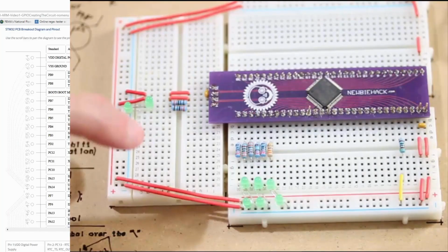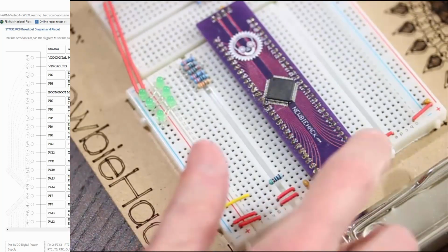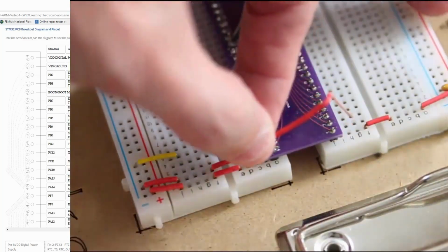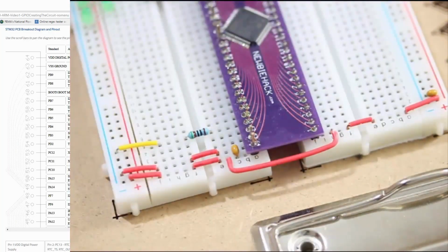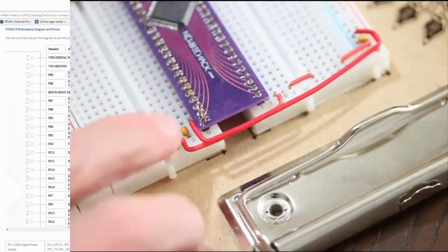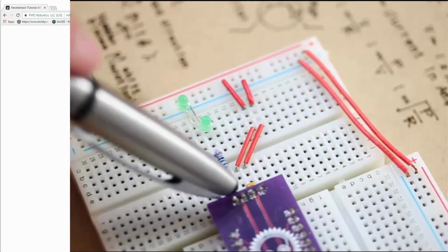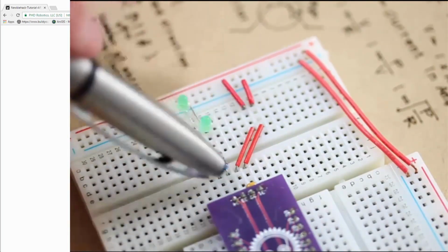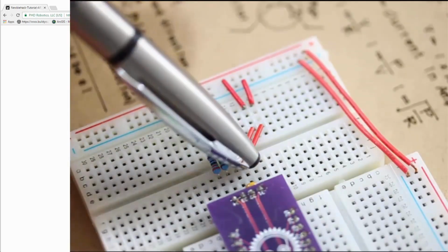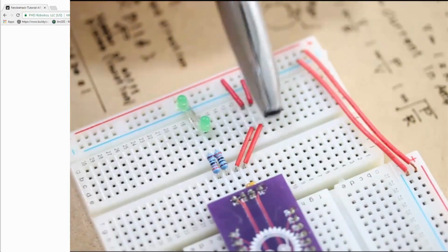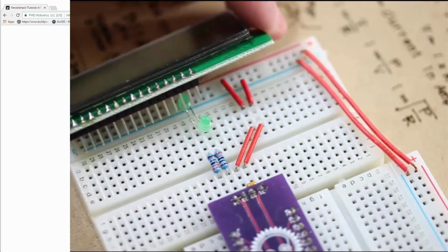So let's get started. I'm going to take these completely out, and I can easily just connect this VDD to this one here. So let's connect the VDD on one side to the VDD on the other side. Now we need to take the ground and put it to the ground rail on the other side. So we have the positive going to the positive, and we have the negative going to the negative rail on the other side. So we have the positive supply, pin number 32, going over from this tie strip to number 11 tie strip and going to the positive rail. And we have the ground, pin number 31, going to tie strip number 10 here, and then going to the negative rail. Now we have more than enough space to put the LCD in.